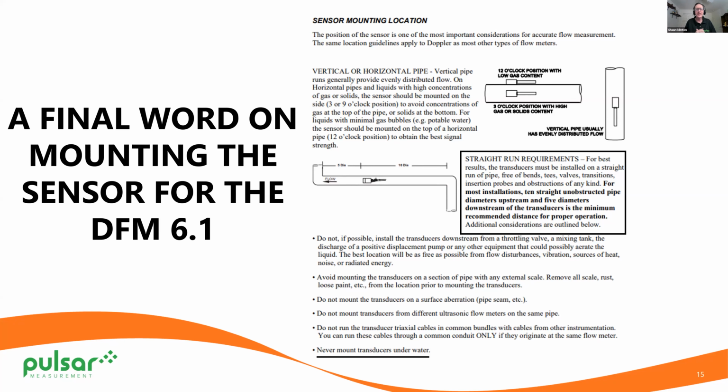And again, you're going to think, oh, it's this equipment, and actually it's not. It's the application. The other thing I would recommend with the sensor is don't put the sensor on the top of the pipe, because if that pipe is just a smidge empty, or you got a lot of air bubbles running through there and it's maybe 99% full or 99.5% full, you just want to make sure. I generally put it at about 3 o'clock.